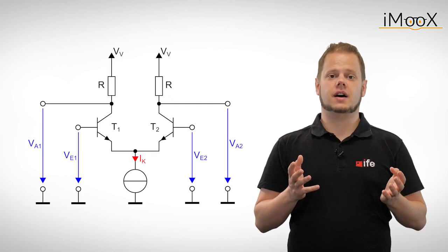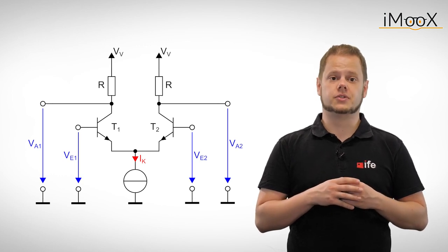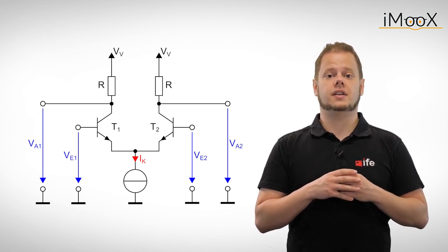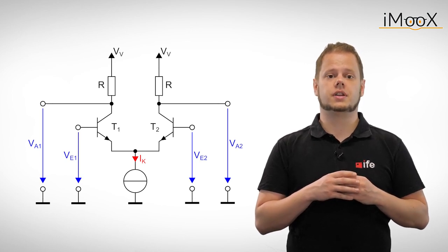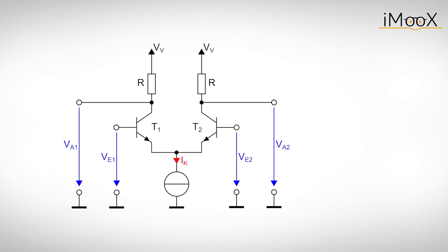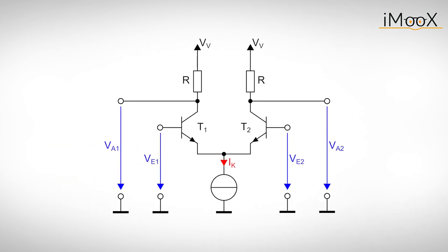The most essential part is the differential amplifier in the input stage. Some quantities defining the performance of an operational amplifier are directly related to the incorporated differential amplifier. A differential amplifier is comprised of two coupled common emitter amplifiers and has in general two inputs and two outputs. In order to understand how a differential amplifier works, we could calculate the impact of the individual input voltages on each output.